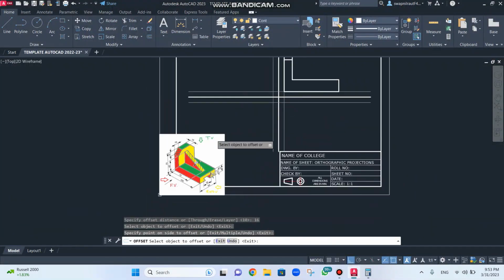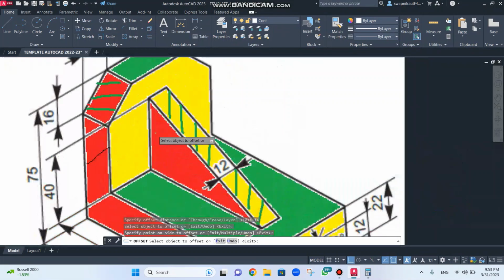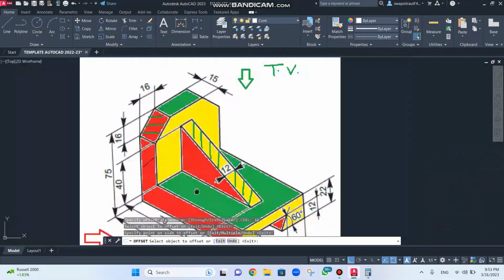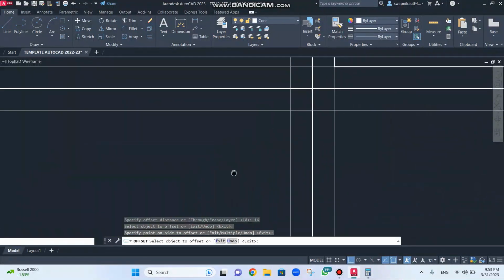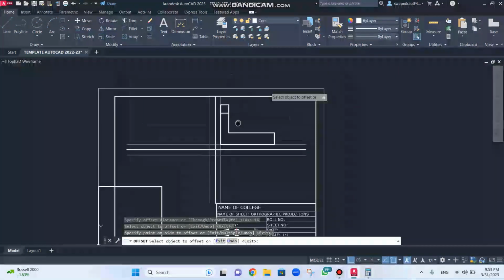Then next, what is visible in the front view is this triangle. For this triangle, we need to draw this slant edge. The distance is given over here, as you can see. From this corner the distance is 70, and from the vertical the distance is 40. Okay, so for this rib, in technical language we call it a rib.